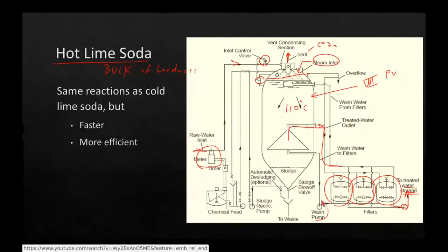One other interesting thing is we've got this backwash pump down here. And so when it's time to backwash these after filters, we're going to take water from, most of the sludge blankets down here, right? So we're going to take this water just where the treated water effluent takeoff is, and we're going to take that softened water and we're going to use it to backwash the individual filters when they require backwashing. Now the effluent from these filters, the backwash effluent, actually goes back into the vessel. So we conserve water in that way.